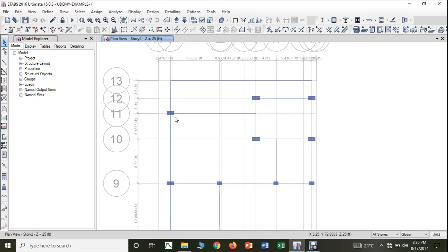And not only that, you have a cantilever projection also. So therefore, more loads will come to this column from these two beams corresponding to this beam. Therefore, if I change the orientation, that will give more stability, and not only that, the eccentricity of this column will be avoided.